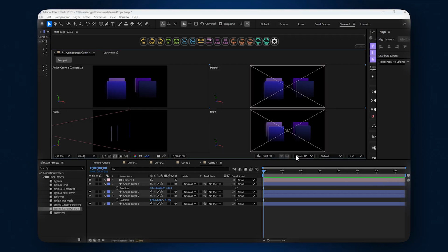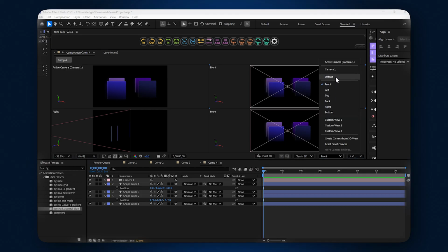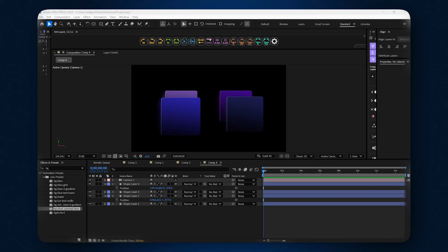Getting more control. Want even more control? Right-click on Position and choose separate dimensions. Now you can control X, Y, and Z movements independently. It's like having 3 separate remote controls for different types of movement, creating smooth paths.